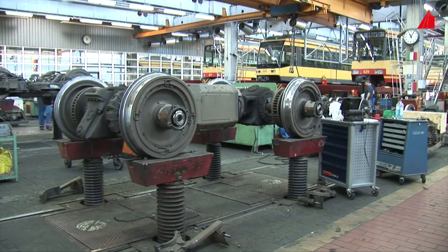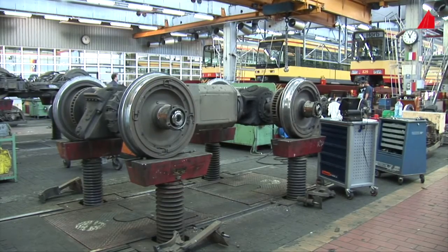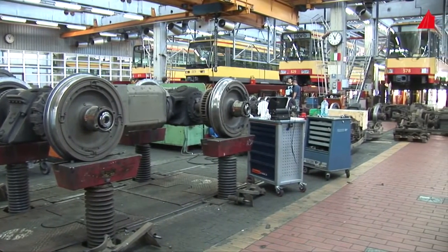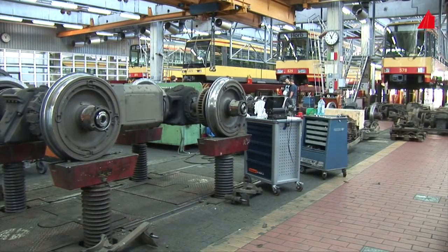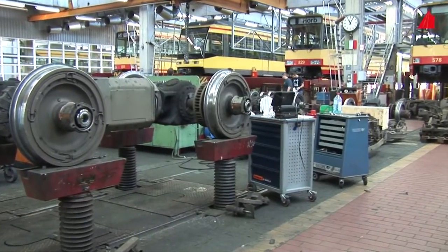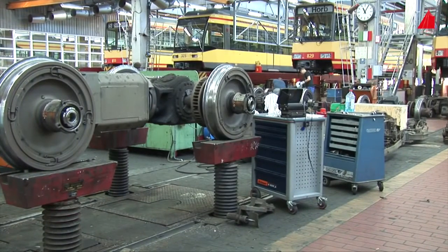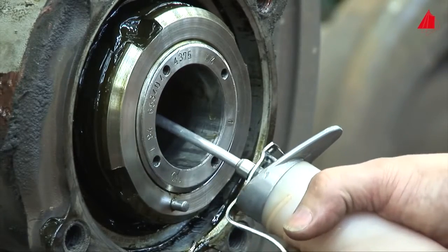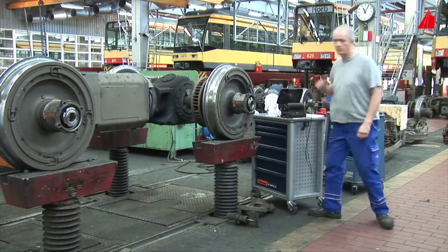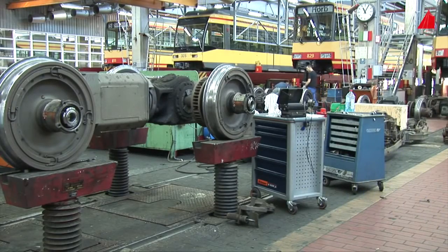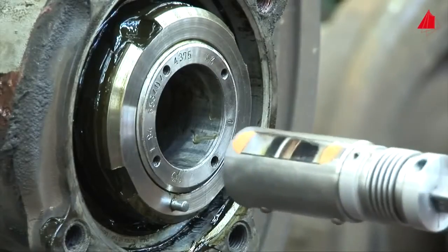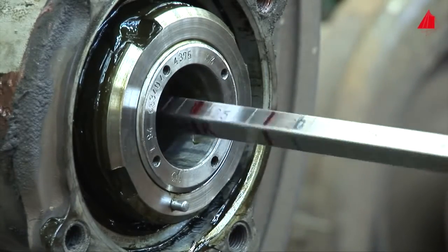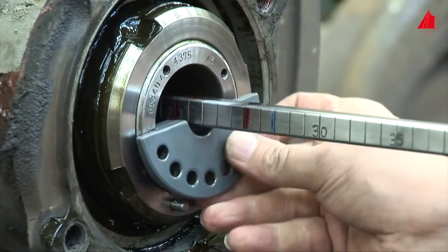This is one of the bogies, jacked up to comfortable working height and prepared for ultrasonic inspection. Special attention is given to the wheel axle, among experts known as wheel set axle. It has been designed as a hollow axle. This saves weight and facilitates the ultrasonic examination. The material tester applies a suitable oil as a couplant into the bore of the axle. Now he takes a special probe designed exactly for this purpose, inserts it carefully into the bore with a mount, and evenly spreads out the couplant by turning and pushing.